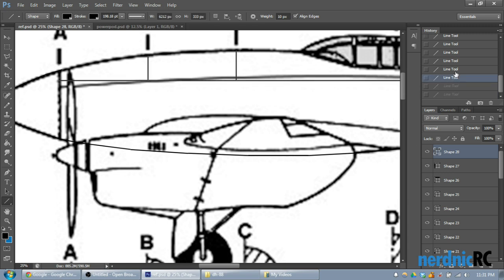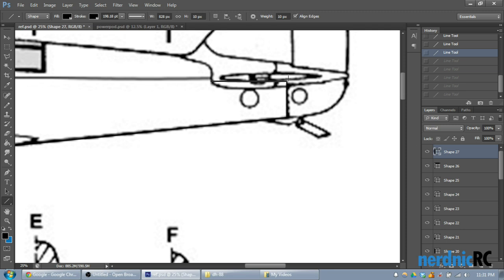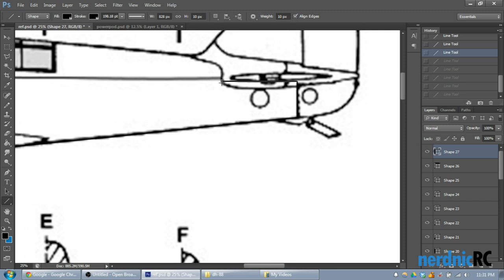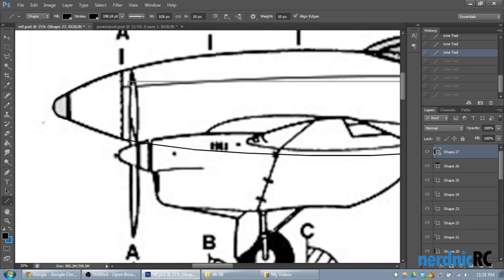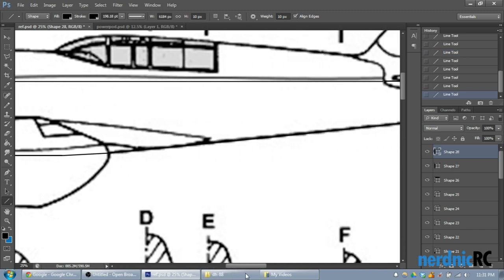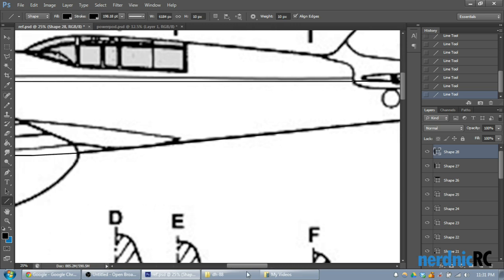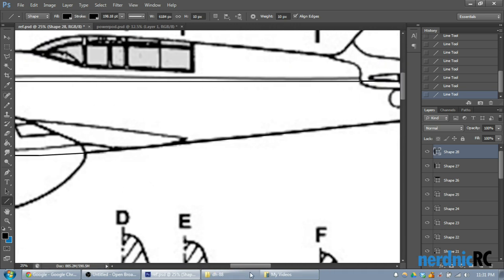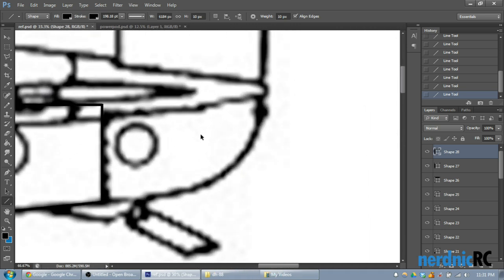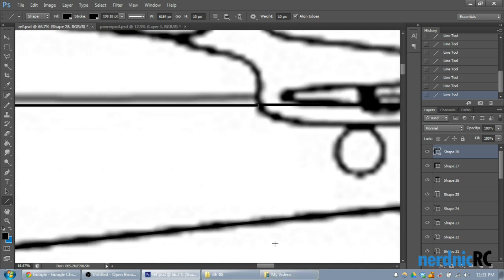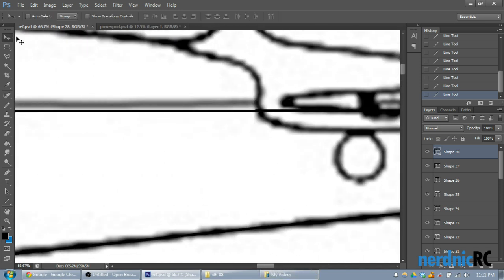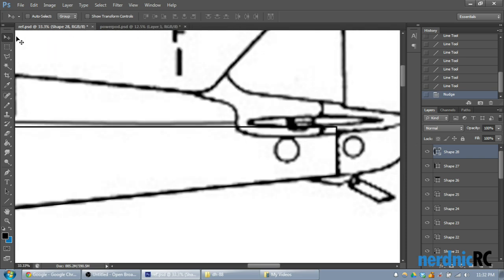So again, this plane ends up being just about right when I'm coming up to the height of the horizontal stabilizer, and then running across, it's basically as good as I'm going to get in terms of the height of the poster board and the former. So this is perfect. In my opinion, this will work great. So we'll bring that up front, and we're going to zoom in here and make sure this actually lines up. So we'll zoom in, and I can see it's a little off, so I'll grab my move tool and click up a few times. And now it's nice and lined up.